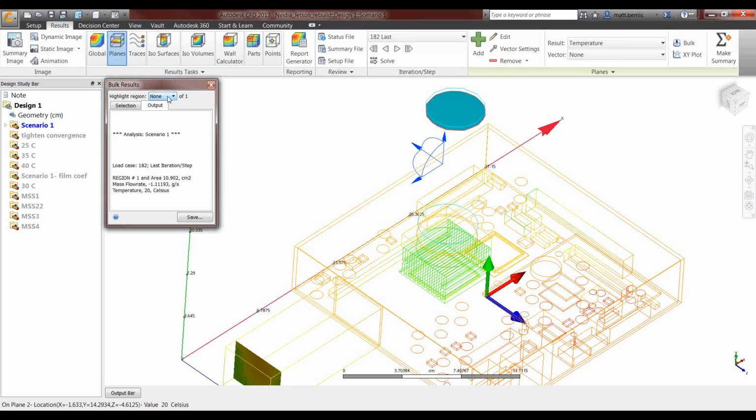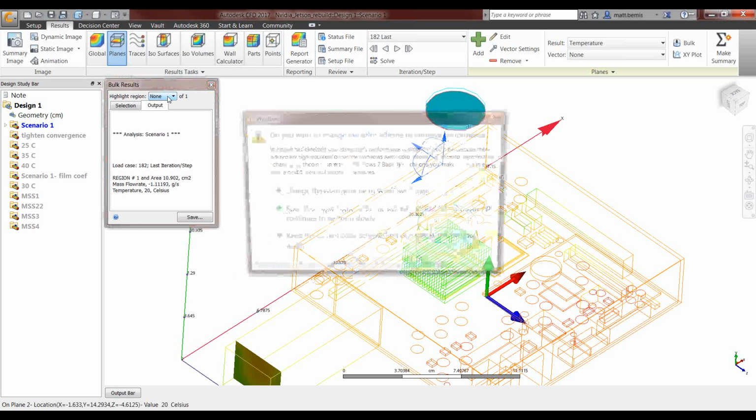So, when we do natural convection studies, we look at basically the max velocities. You're generally going to see, I guess probably 20 to 30 inches a second is a high velocity, at least in that ballpark. That's a pretty slow flow there, and at times mixing length can be more appropriate. I usually end up trying both and looking at the results.